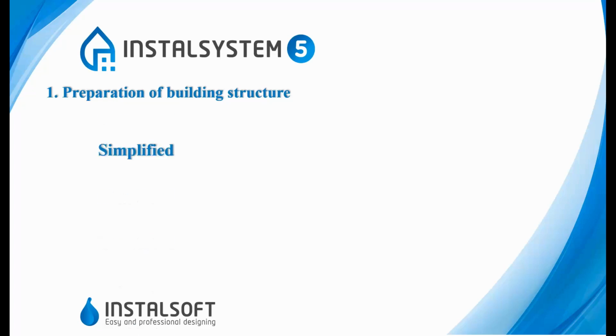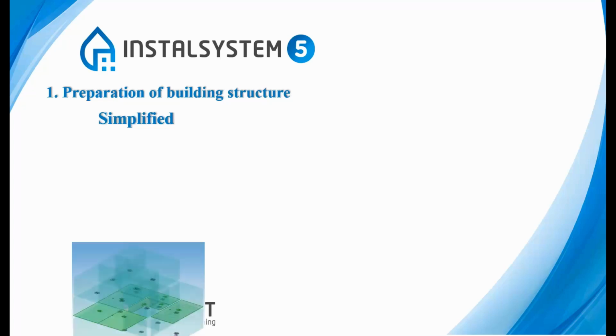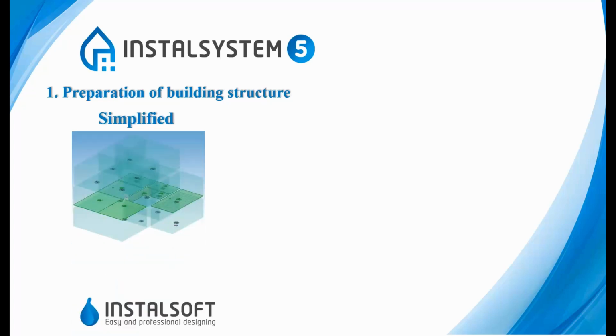And there are two ways, two scenarios of building structure preparation. The first one, simplified, where rooms are represented by cuboids, as you can see on this little preview. And in this case, we can do it very quickly, but we cannot calculate precisely heat losses. Heat losses need to be estimated or imposed. Estimated using the heat loss coefficient, or just imposed manually.